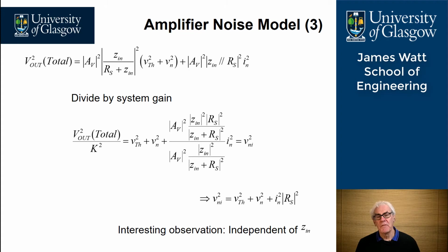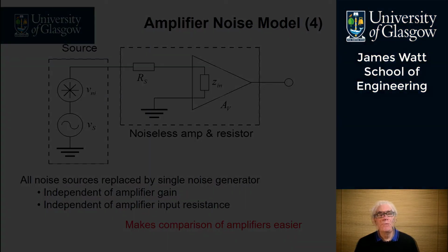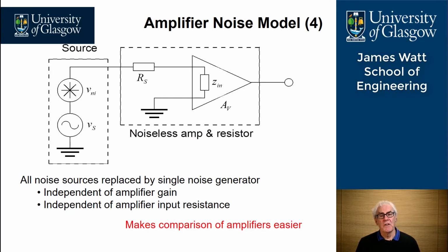An interesting observation we can draw from this is that the actual input impedance of the amplifier is not important in this equation. It's actually only the source resistance that gives rise to the calculation of the total noise squared at the output of the amplifier.